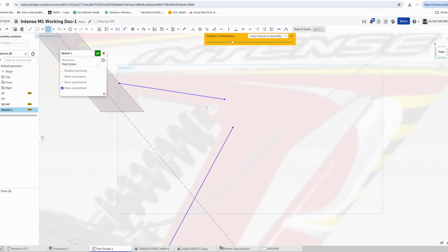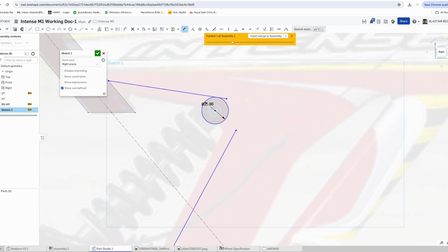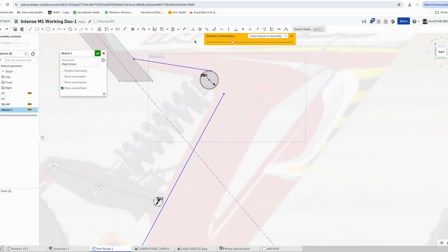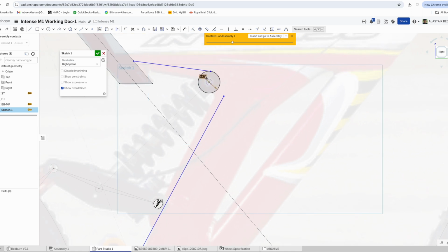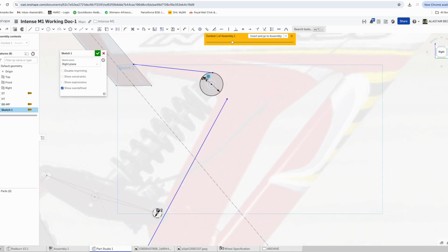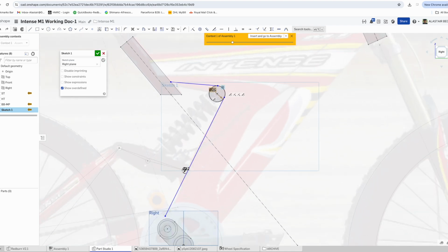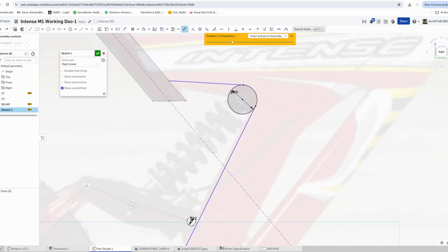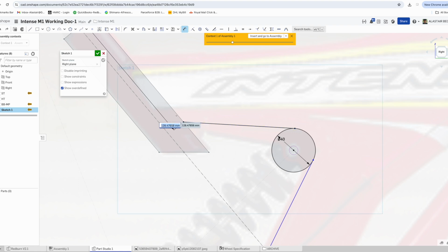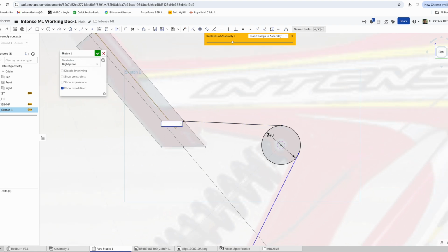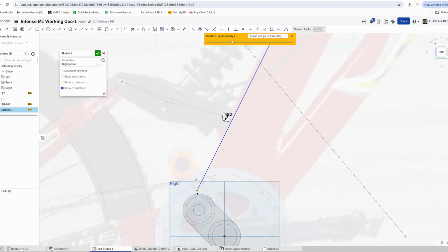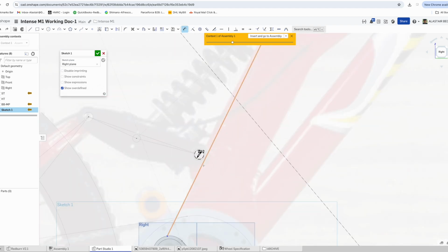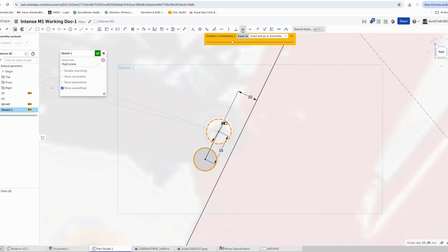Again, the way I'm laying this out in this scenario is just to have a front triangle sketch that I'll create a subassembly from. So I'm going to create a front triangle subassembly after all of this, and then that's when I'll start doing my modeling. The reason for that is the full frame is going to be made up of a front triangle, a rear, seat stays and chain stays and a rocker link, and the front triangle comprises a couple of different tubes, so it's a subassembly in its own right. So we've got to start somewhere though, so we're starting in this main general assembly file.